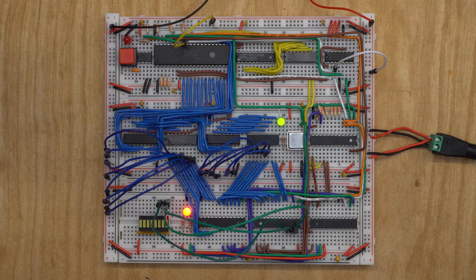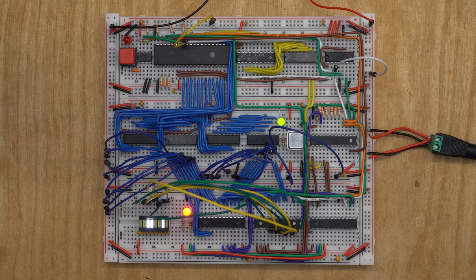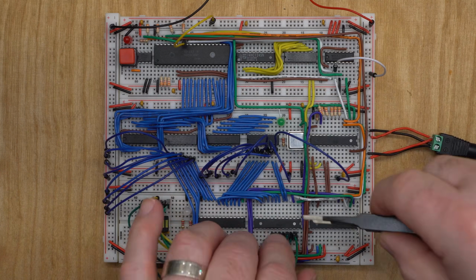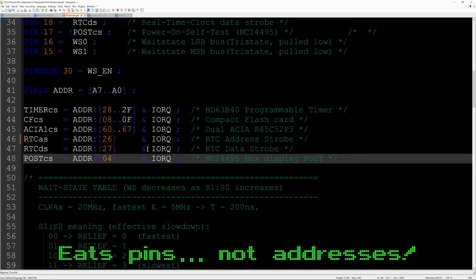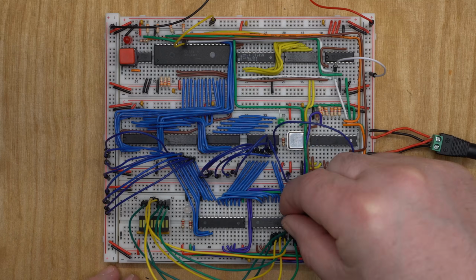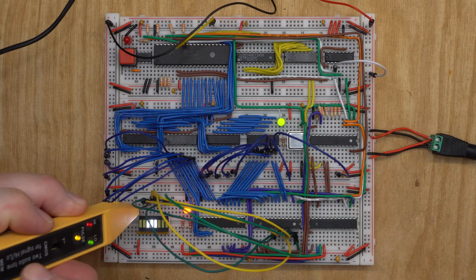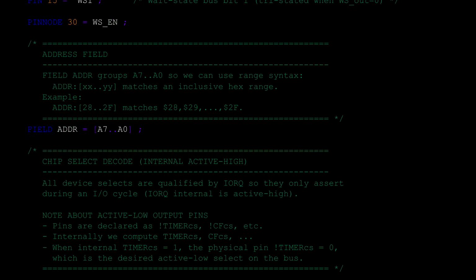Up next, the I/O decode PLD. I walked through all 7 chip selects, or really 5 since the RTC eats 3 addresses like it owns the place. And yes, there was an addressing issue with the RTC chip select. That got corrected. Then came the wait state logic.